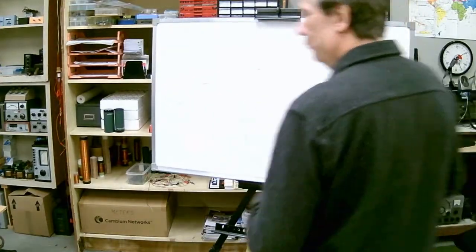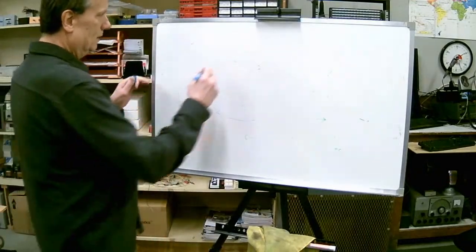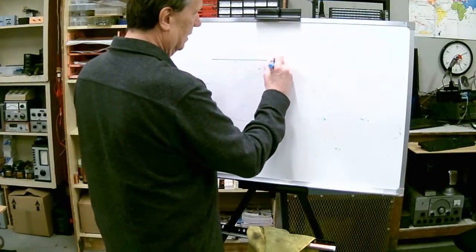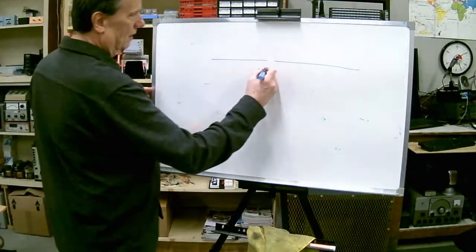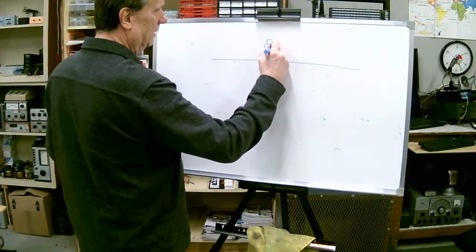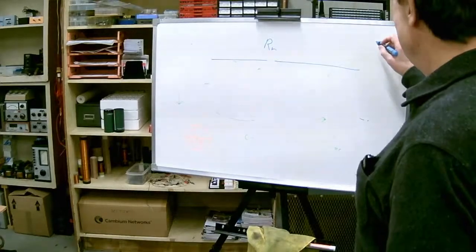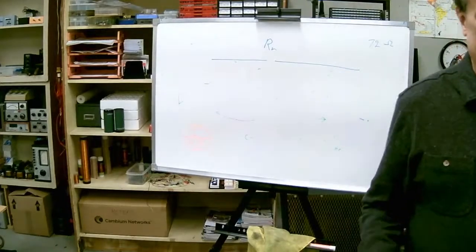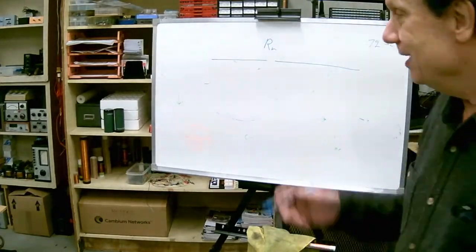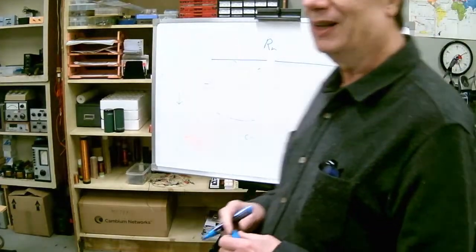So, in free space, with no other objects around, a half wavelength dipole, and again, this is at any frequency as long as it's a half wavelength, whatever frequency you pick, this mysterious R sub R, radiation resistance, at the feed point in the middle is going to be 72 ohms. That's in free space. Once we have reflections off the ground or whatever, it's going to change, but 72 ohms is your radiation resistance in free space, regardless of the wavelength or frequency for a half-wave dipole antenna.